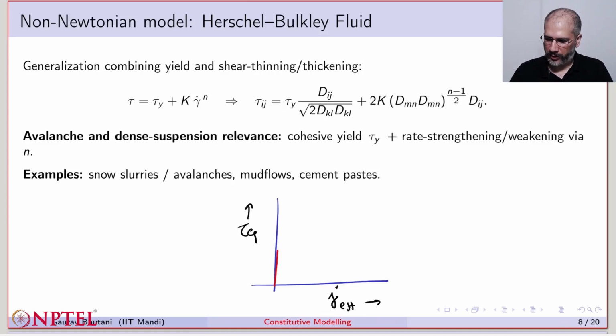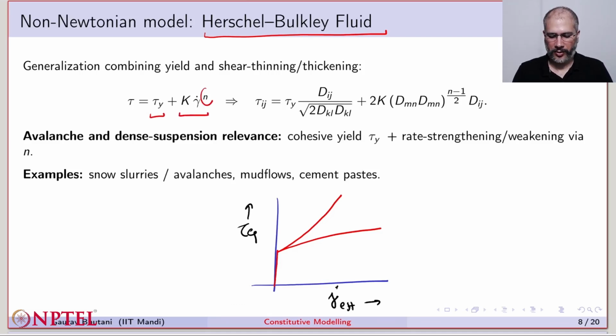What that basically means is that we may have a shear thickening or a shear thinning behavior along with the yielding behavior in a Bingham fluid. So these fluids, which combine the idea of yielding and nonlinearity, are called Herschel-Bulkley fluids. So in 1D, it shows a yielding stress and a power law kind of behavior with an index n.